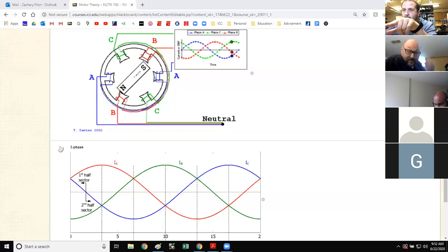Inside of there is a set of magnets that's spinning around these windings. And then the amount of current that gets generated, say through winding set A, the blue one, depends on how quickly the magnetic lines of flux are being cut. And that's really going to be hard for me to show you virtually, but picture it this way. If you've got, let's say, a winding up here.